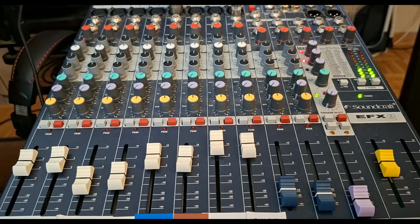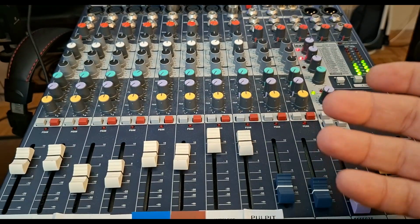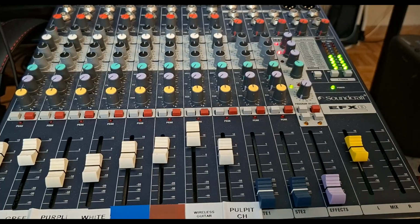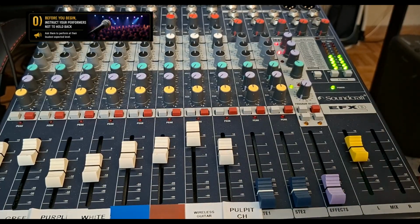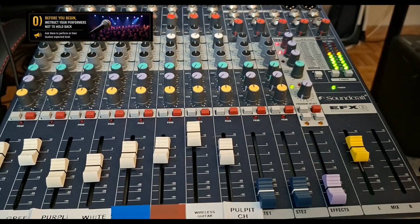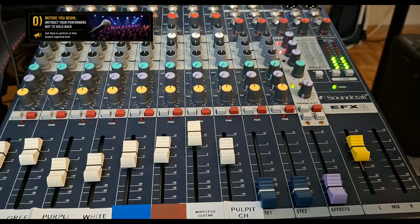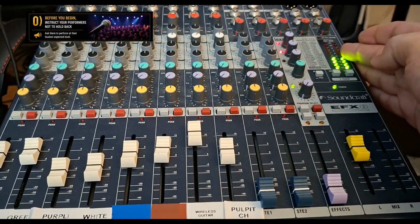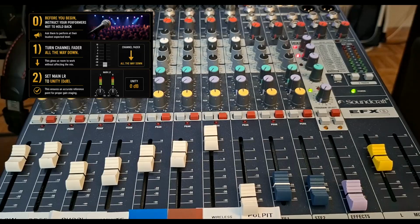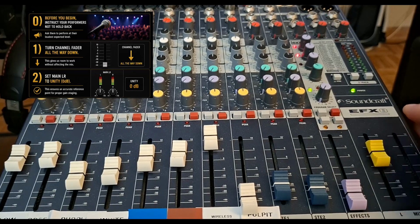Now let's talk about proper by-the-book gain structure. This is the procedure I like to teach new operators to follow. Now, before you are doing this, you are going to have to communicate with your musicians or speakers to make sure that they are singing as if this was a live performance. That way, you ensure an accurate reading on your meter. Step 1. Turn the fader down. Set your main left and right output fader at unity or 0 dBs.